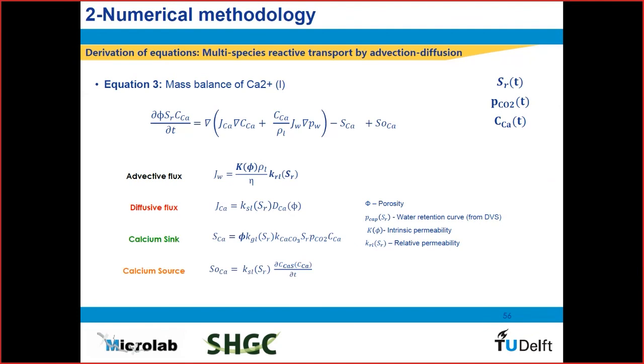And then at last we have the mass balance of the calcium in the pore solution. In this case, we can no longer neglect the advective flux of calcium with the speed of the moisture flow, because this is quite relevant here. The calcium dissolution from the hydrates is quite fast, so there is a lot of time for it to actually transport through advection to other parts of the domain before the reaction occurs. So this needs to be considered, and it's the second term in the brackets.